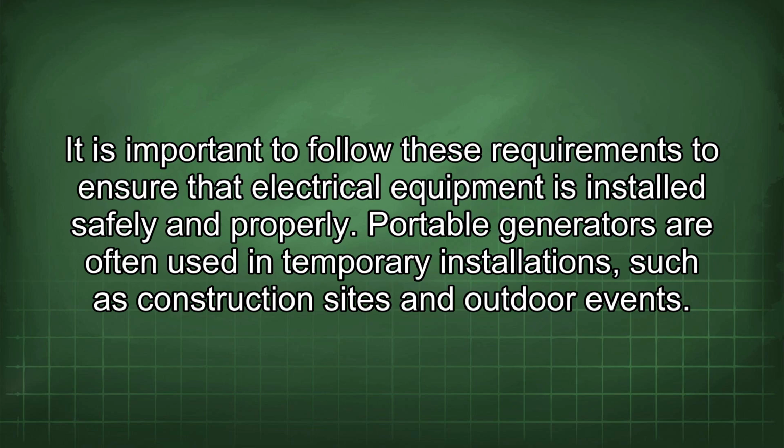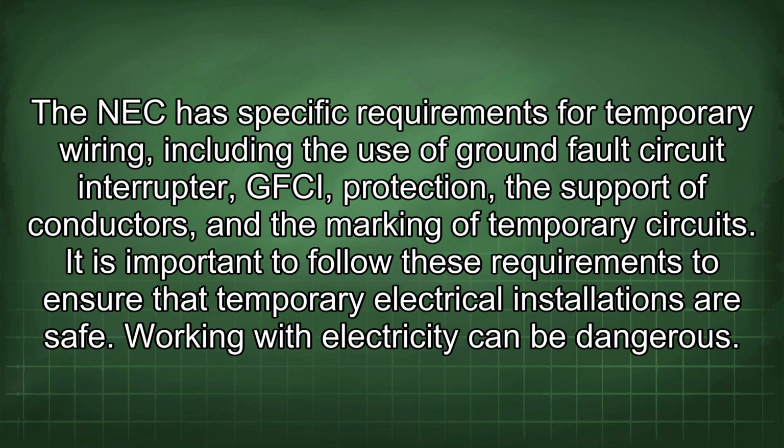Portable generators are often used in temporary installations such as construction sites and outdoor events. The NEC has specific requirements for temporary wiring, including the use of ground fault circuit interrupter, GFCI, protection, the support of conductors, and the marking of temporary circuits. It is important to follow these requirements to ensure that temporary electrical installations are safe.